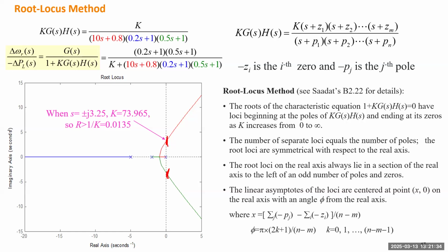Okay, but there are some other root loci that will go to infinity by a certain angle, not stay on the real axis. So that angle can be solved by here. For this case, that angle is 60 degrees. If you have a more complex situation, you will see the root loci will have a more weird shape, but that can be estimated here. Definitely, we don't need to do that anymore. But this one gives you a better visualization of why the system can lose stability.